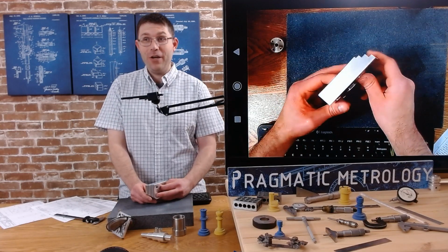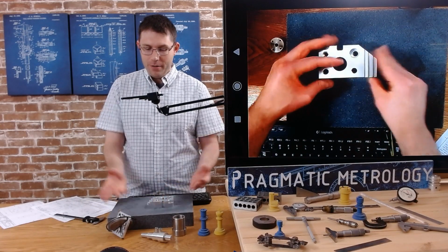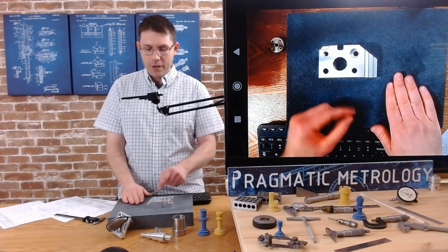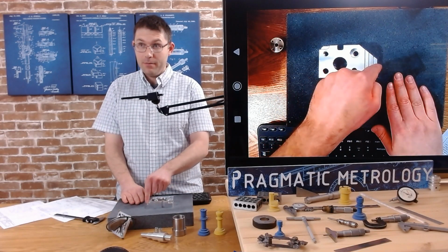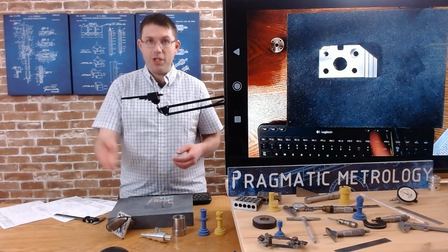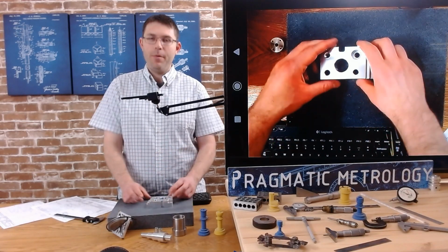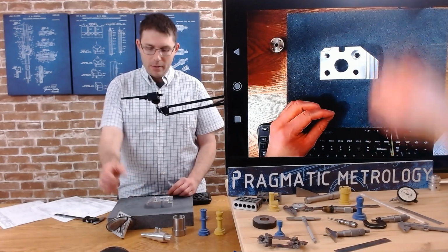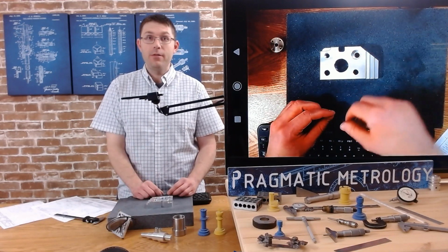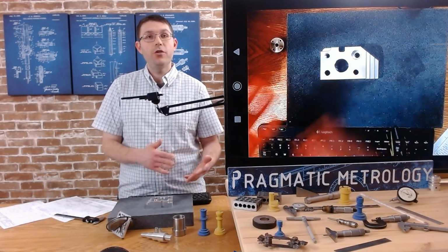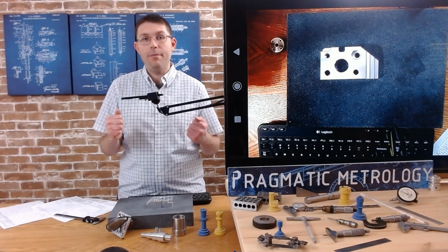Getting back on track. If you could change this to datum A, well, then you could do direct depths of these steps, and that might be easier. That might make everybody happier. Machining will be happier. They'll be able to run the part in the order they want, and inspection will be able to get direct methods. And if it doesn't affect part functionality, hey, everybody's happy.